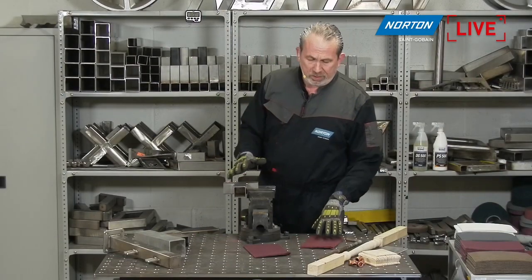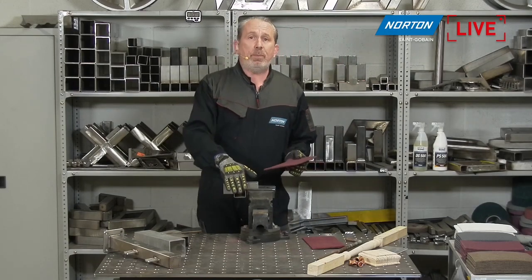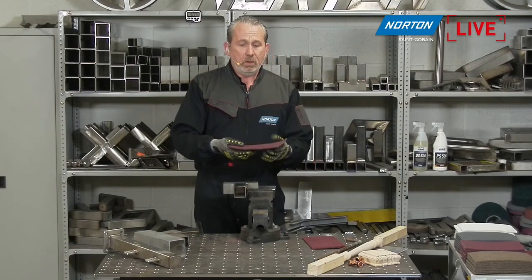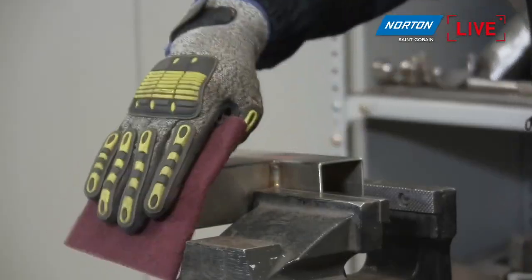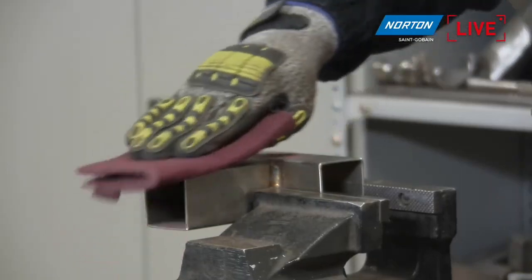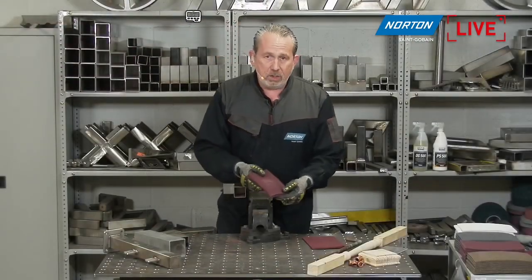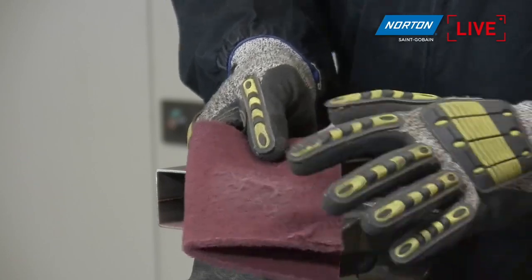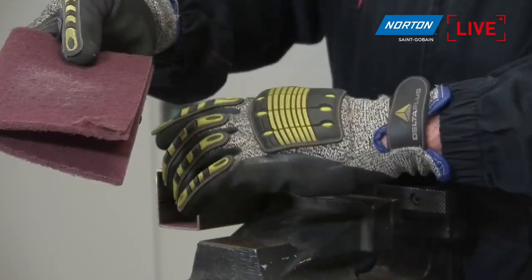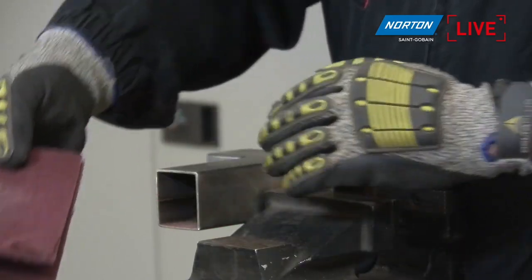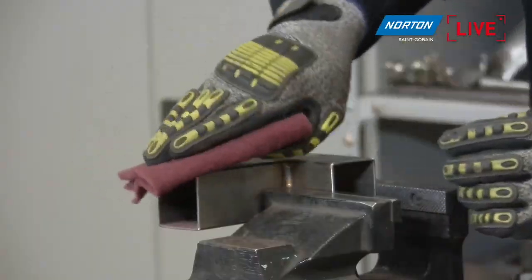Another way to check the quality of the hand pad and give you an idea of how long the hand pad is going to last is do a test on a sharp edge, such as this bit of steel we've got in the vise here. If we fold the pad in half, and we just rub that over the edge. If we do that 10 times for each pad, 7, 8, 9, 10. Okay, we can have a look at the surface of the pad and how that looks. If we just go back to that camera, please, Martin. We've moved a bit of the fiber on there. Okay, but it's still very well intact on that hard application over an edge where it's almost deburring, if you like. But when we use a slightly inferior pad, we can do the same again. We do 10 rubs on here.